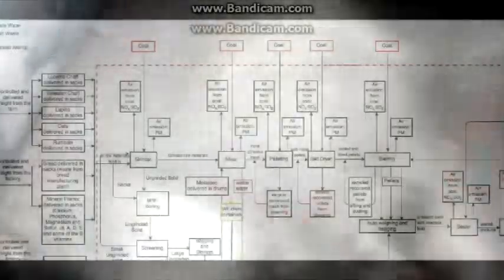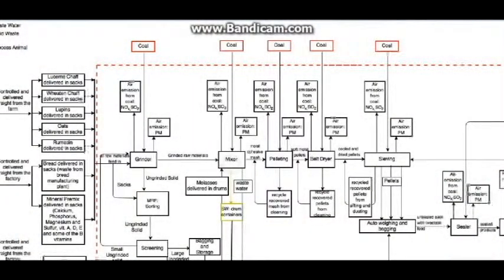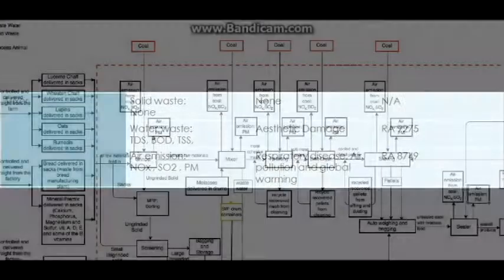Mixer. Grinded raw materials are mixed in this process, while adding molasses as binding agent. The drums of the molasses will then go to the drum filling process as for the sludge. There is a wastewater stream from the cleaning of the mixer. The output from the mixer is a cohesive mash which will go to pelleting.